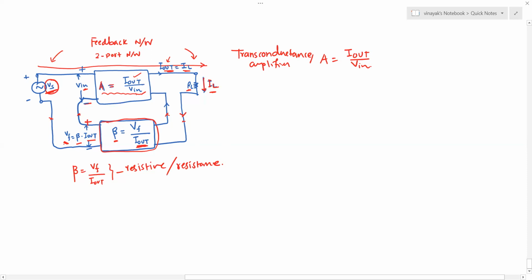Usually if it is a negative feedback, so the positive and the negative that appears here, which is the Vn, is then the difference between the input source voltage and the feedback voltage, Vs minus Vf in case of negative feedback. Okay, and then again this error voltage, the difference voltage between the two, is being given to the amplifier, which is the transconductance amplifier.